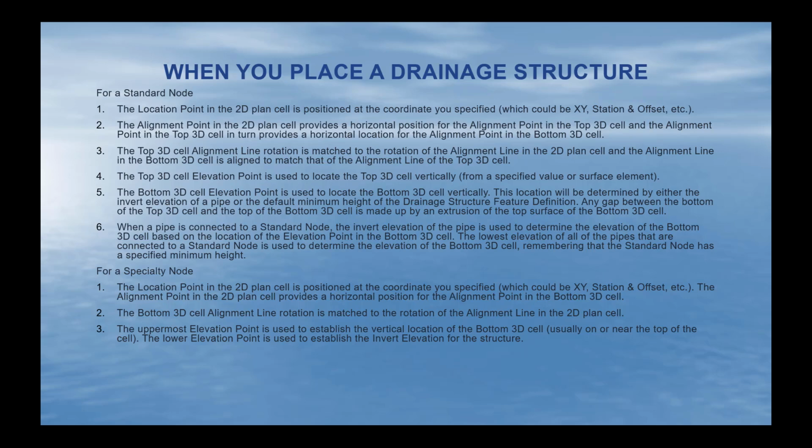The inverse is not always true. You may be restricted from raising the elevation by using the bottom cell point or the invert of the structure. So changing that value may or may not allow you to raise your pipe invert elevations.